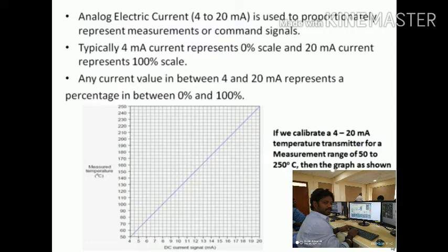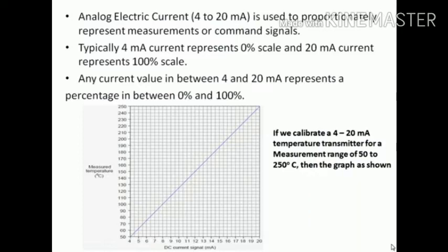What I'm trying to say is, when an electrical officer measures some value between 4 and 20 milliamps, how do we know that milliamp value is exactly what the pressure is showing? Whether both are equal or not, or whether we need to change the sensor or calibrate, we can find out so many things. For that purpose we will see the formula, and with the formula we will do some practical solutions also.